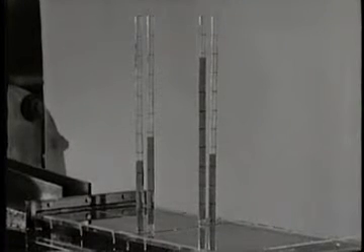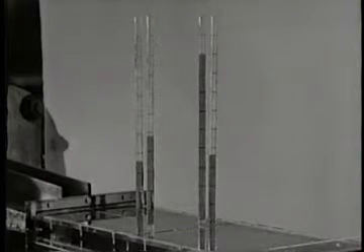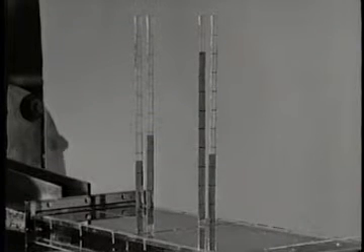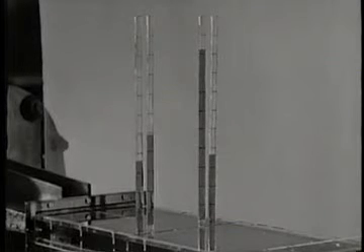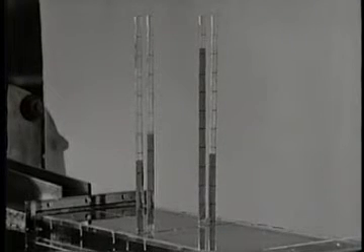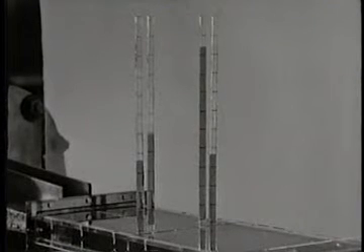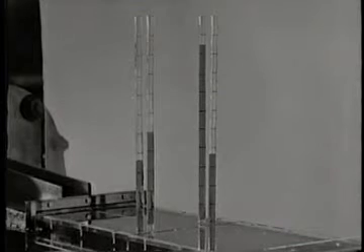The reason Bernoulli's integral cannot be used here is that we are dealing with different streamlines. Because of the confinement of the channel walls, the streamlines are straight, with no curvature, and no normal pressure gradient. So the pressures on the two sides are the same, even though the velocities differ. For the same reason, the pressure across a viscous boundary layer is virtually constant.